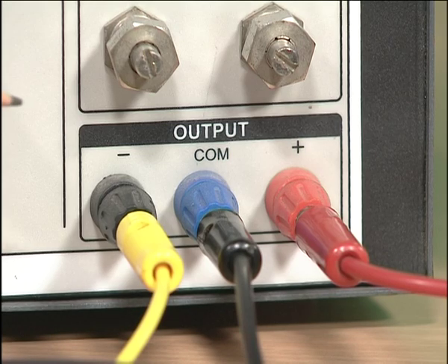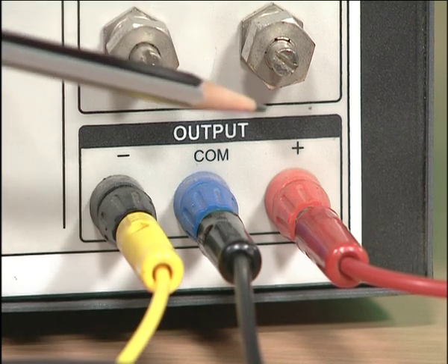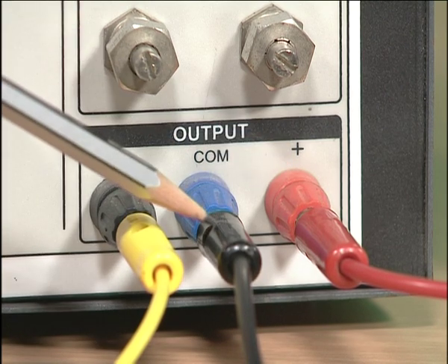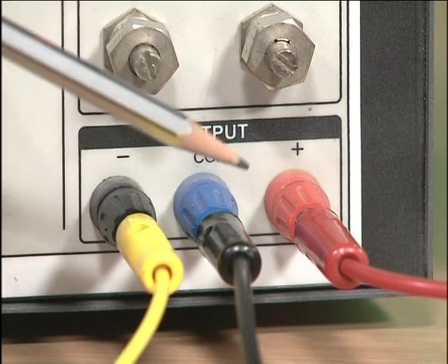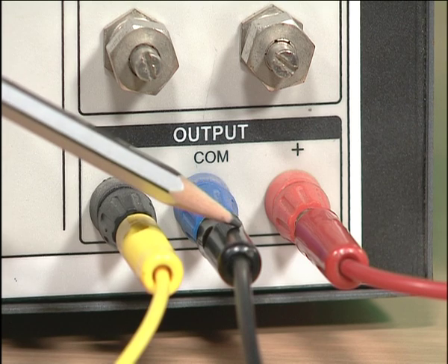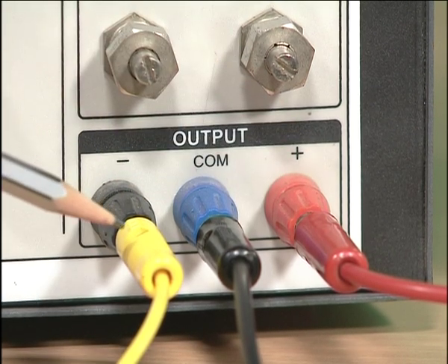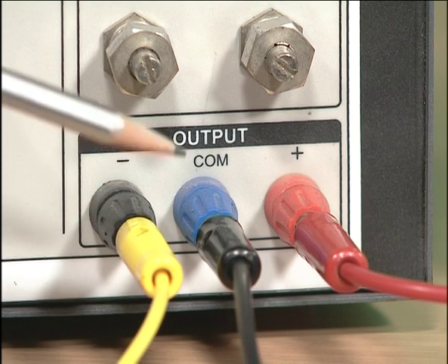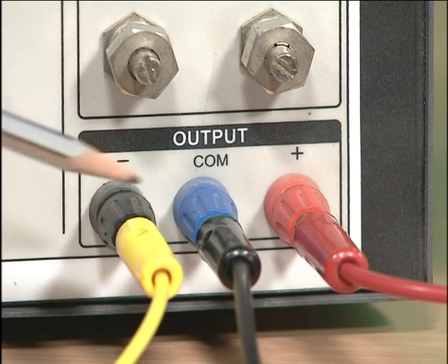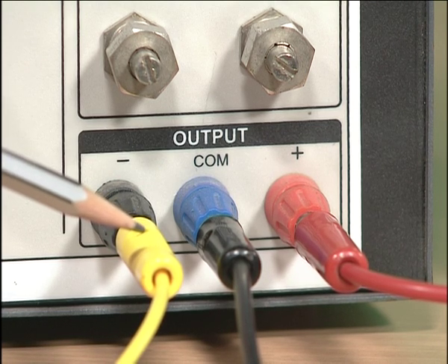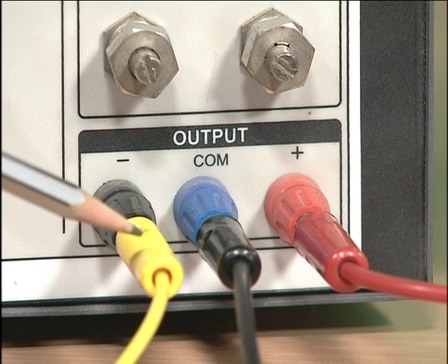The supply voltage is derived from a DC supply source. Plus 12 volts is derived between the plus terminal and the common terminal, which is a ground terminal, and this plus 12 volts is connected to the 7th pin. The negative voltage, which is minus 12 volts, is derived between the minus terminal and the ground, and this negative voltage is connected to the negative supply pin of IC 741, which is the 4th pin.